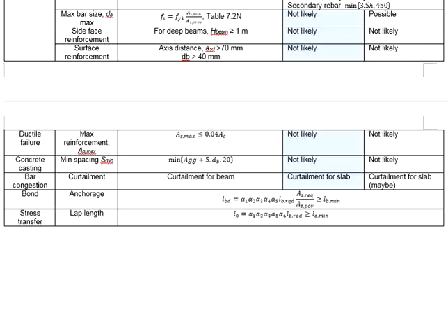As the industrial practice in the construction site, they are using the inches and feet instead of the SI unit. In fact, the required anchorage length and the lap length is given in the British standard also. Industrial people prefer to use British standard to determine the anchorage length and the lap length, which normally end up somewhere between 46 to 50 times the bar diameter for typical concrete.